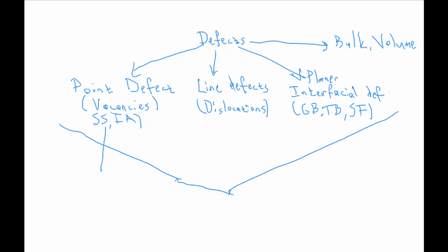So we know how interstitial, substitutional, precipitate defects affect the strength of a material, right? We have solid solution hardening, and we basically have one dislocation stress field. If it is edge, it will create tensile and compressive fields.